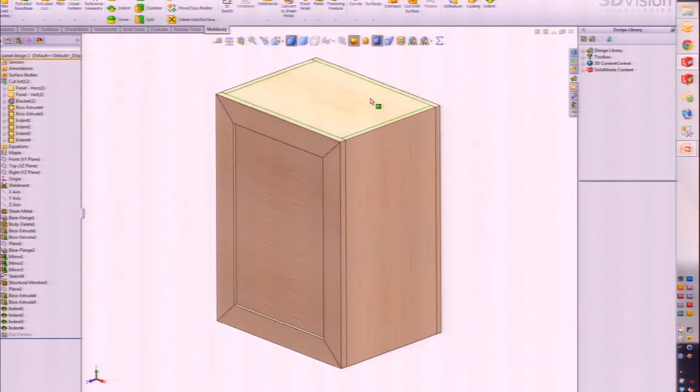All right. So what's going on here now is there is something called a cut list being built. All right. So right up there. That's similar to a bill of material inside of an assembly file, okay? It's a list of all the bodies that exist inside of this single part file, okay?